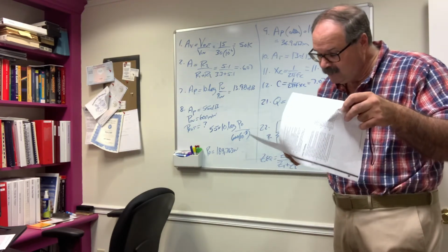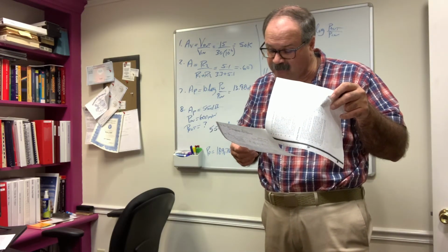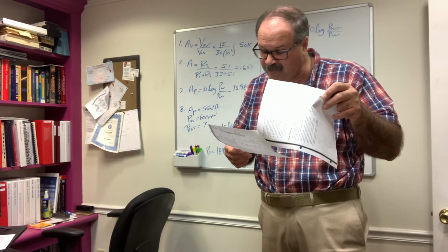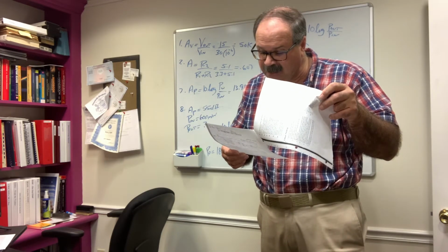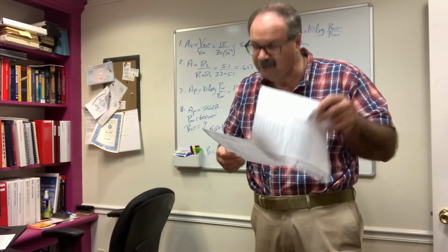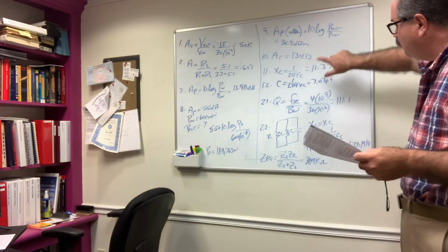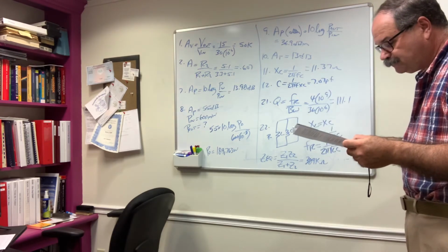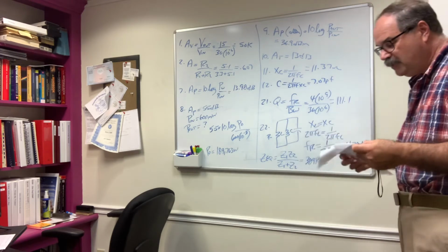Question 10. A communication system has 5 stages with gains and attenuations of 12, minus 45, 68, minus 31, and 9 dBs respectively. What is the overall gain? Since they are already expressed as dBs, we can simply add these together. Overall gain is going to be 13 dB.